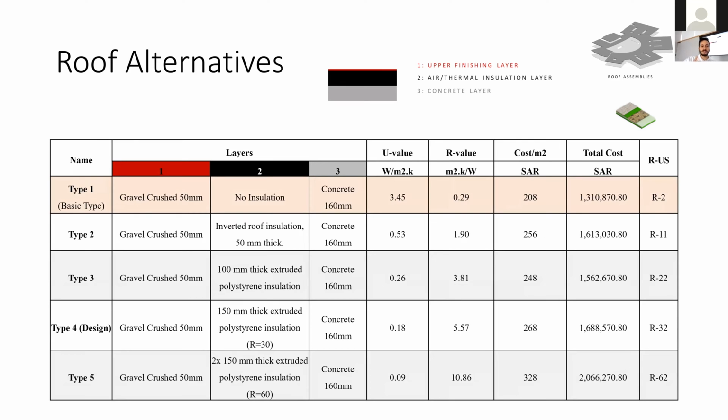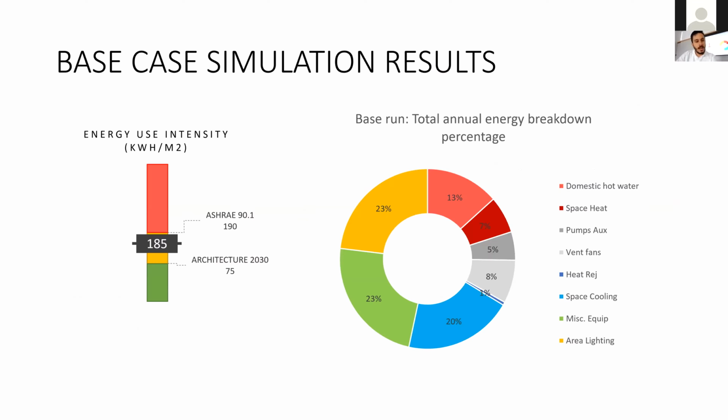And we tried different thicknesses of insulation in order to see which thickness would be more efficient, because of course as you increase the thickness, the price would increase. So we had to do some value engineering in there and make sure that we don't go to the highest option, where there wouldn't be a lot of savings. So we had to do a sensitivity analysis on that. And this is what the results of one of the cases would look like.